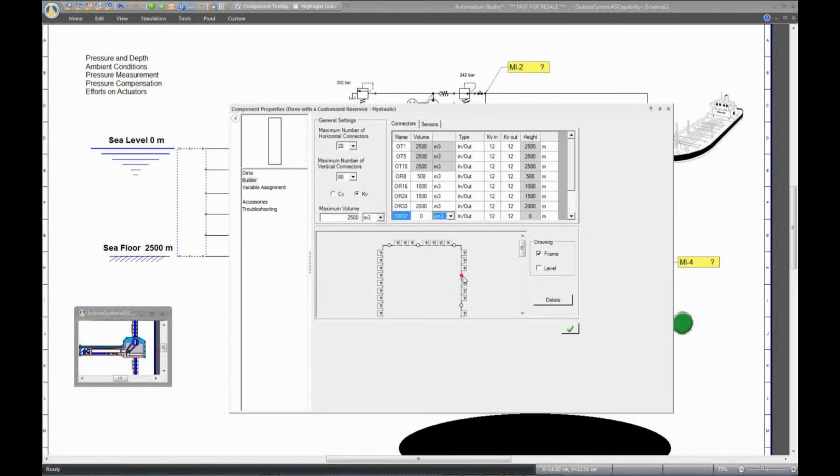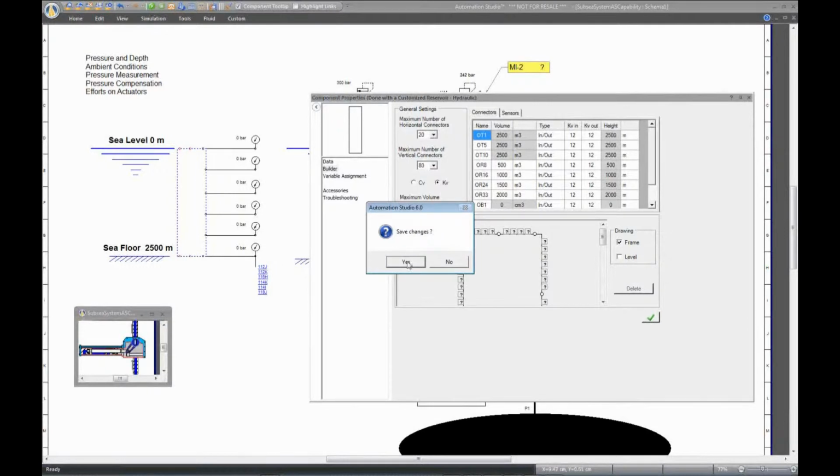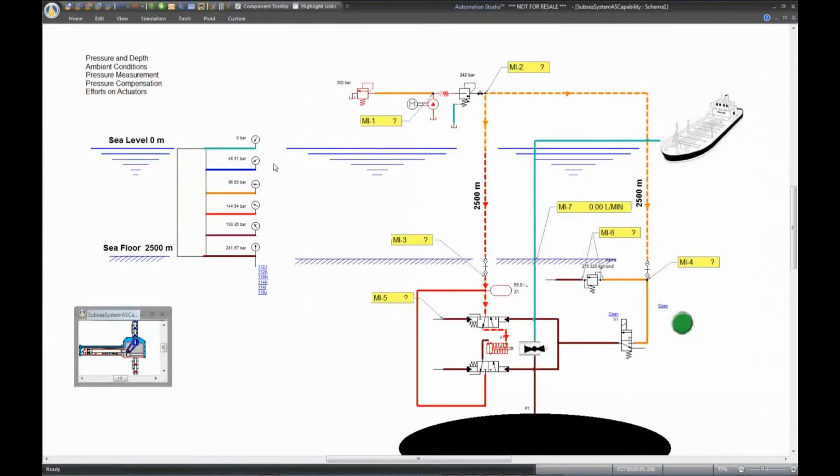I have already configured the example, and I have declared, I think, 6 ports, not really important in themselves, but to illustrate different pressure levels. And you will see that when I start my simulation, we can see different hydrostatic pressures that are built because of the simulation. This pressure, of course, depends on the fluid used in the circuit, and I have used water.